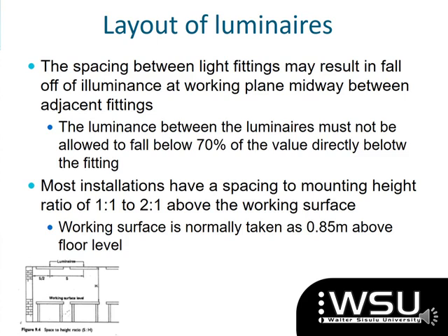Now, here's another thing. If you remember in examples 2 and 3, we had a difference where one was looking at a ground level and another one was looking at a bench. All right. So we usually say that our working surface, when you are indoors, is at a level of 0.85 above ground level.